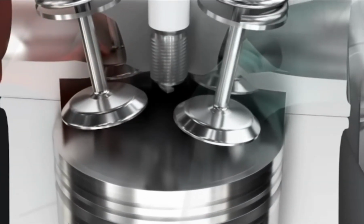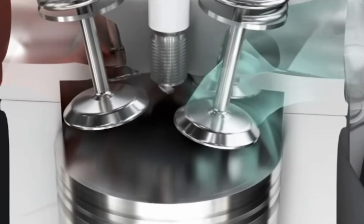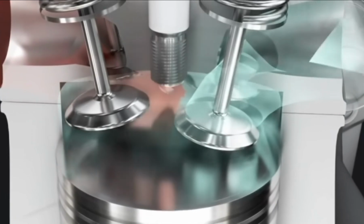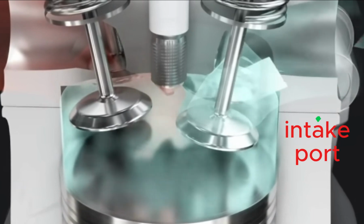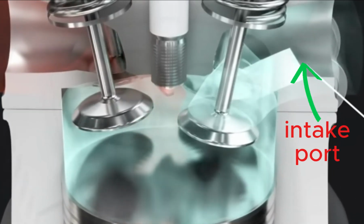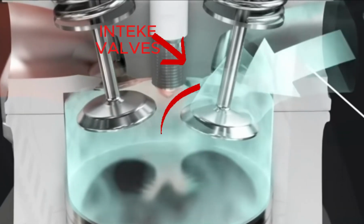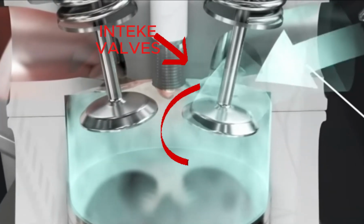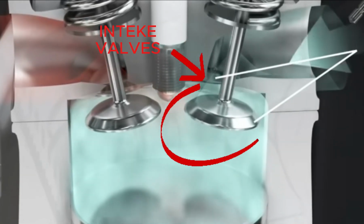The intake valve opens, allowing air or an air-fuel mixture to enter the combustion chamber. In gasoline engines, fuel is mixed with air before entering the cylinder, port fuel injection, or injected directly into the cylinder, GDI, gasoline direct injection. In diesel engines, only air is drawn in during this stroke. Fuel is injected later during the compression stroke.